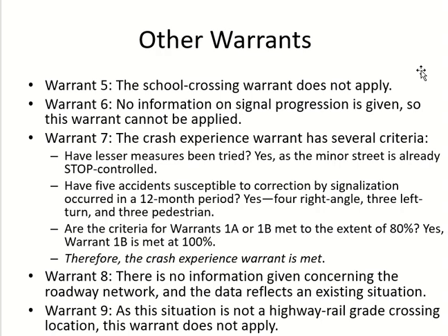And then we have other warrants as well. For example, warrant for pedestrian crossing. Warrant for school crossing. Okay, it's not near a school, or even if it is, it's not given. We cannot use it. A warrant for signal progression. Signal progression means you already have signals which are around it. Okay, and this is the only unsignalized intersection. Okay, so it will make it better if you signalize it as well. But the information is not given about the other intersections. I cannot do it. Okay.